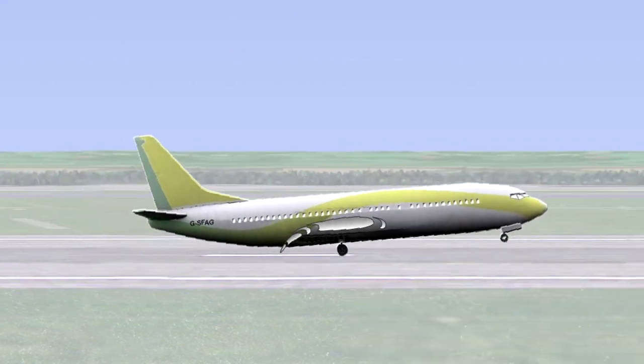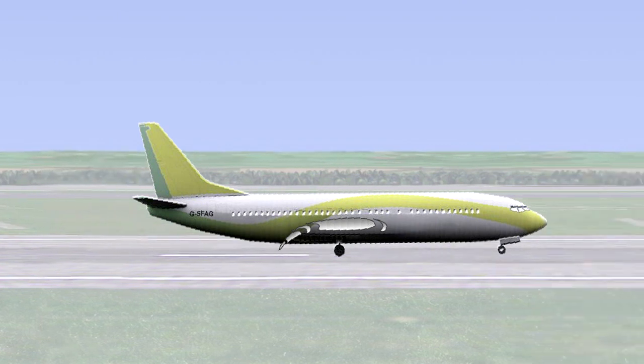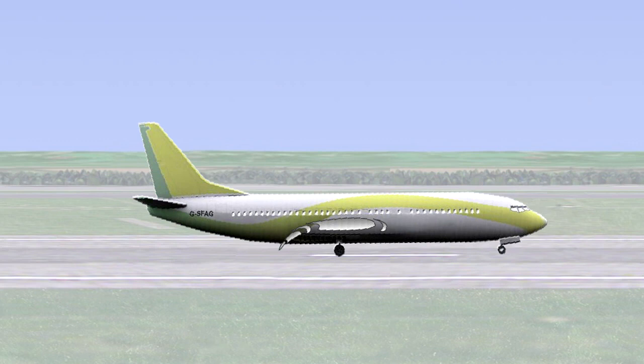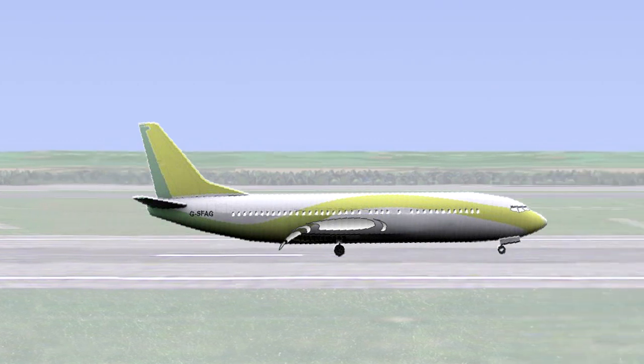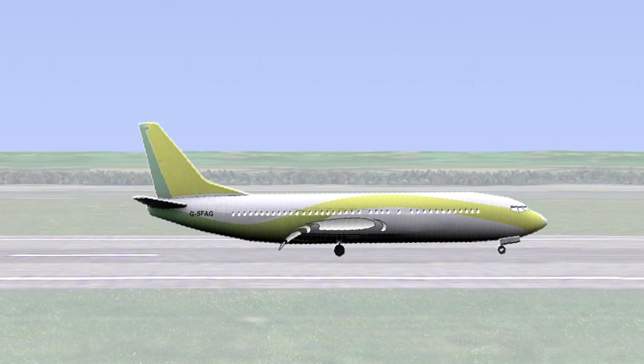After main gear touchdown, do not hold the nose wheel off the runway. Smoothly fly the nose wheel onto the runway by relaxing aft control column pressure. Raise spoilers as soon as possible after touchdown or confirm auto spoiler deployment. If the aeroplane does not have auto brakes, then initiate braking once spoilers have been raised and nose wheel has contacted the runway. Apply brakes smoothly and symmetrically.